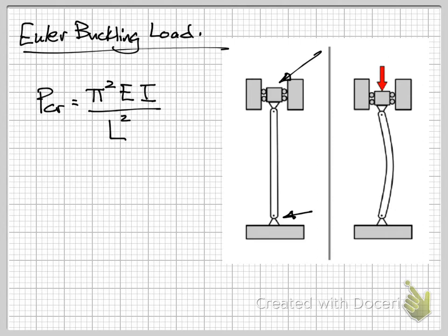Sometimes people refer to this as a pin, but it's much more like a roller, because the column is only constrained in the lateral direction here at the top. It can still move vertically and it still is released as a moment because this is a pin.